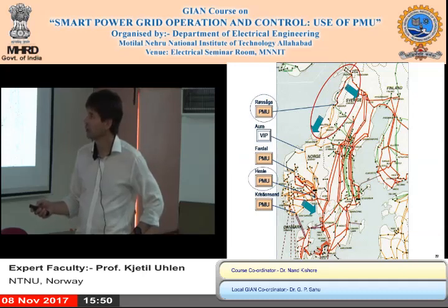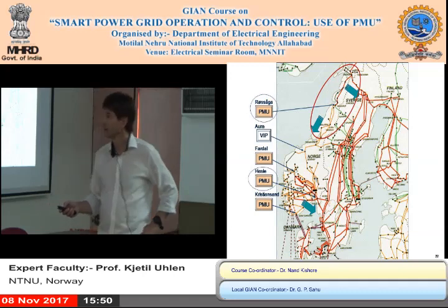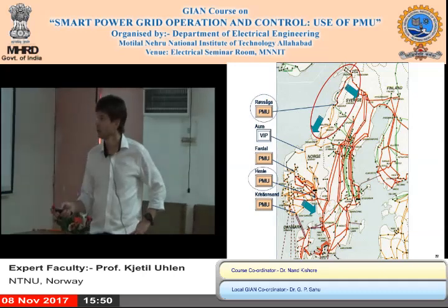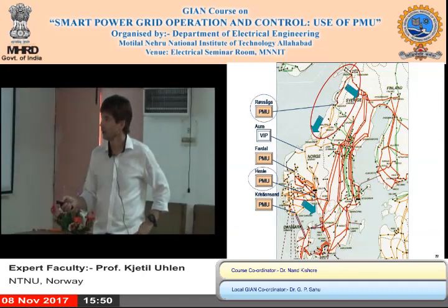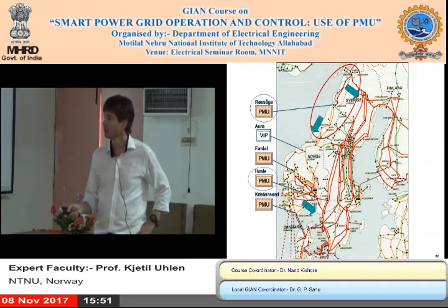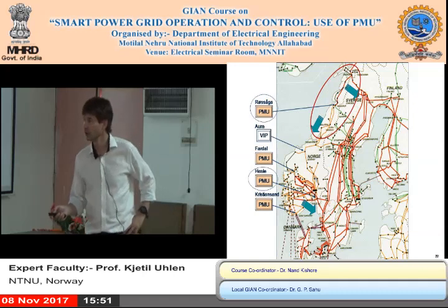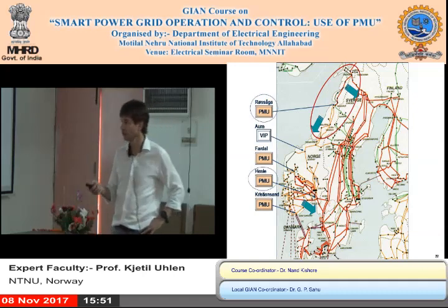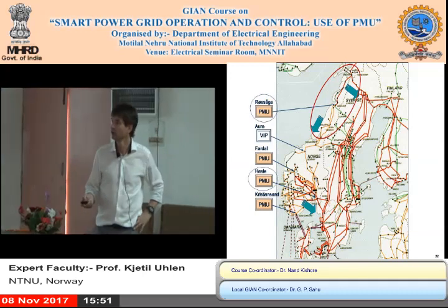Then there was a fault up here, and this line was shut. Then you had an overload on these lines, and this area became an island. All the power that was supplying the grid from this area was out. So you get a lot of power reserves activated here, flowing across this border, and overloaded those lines to a certain extent. Not overloaded, but at the risk of that.